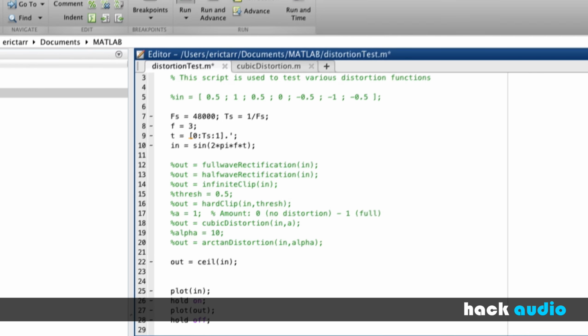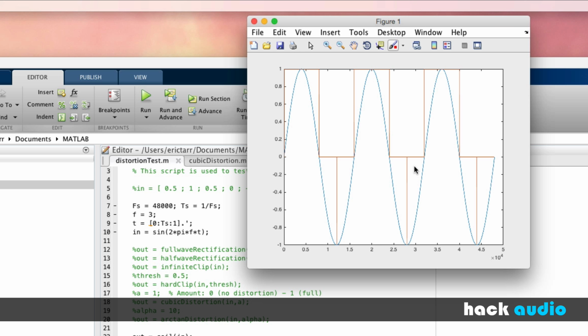It's going to round things up. So we're always rounding up to the nearest integer. As soon as our input signal has a value that's greater than 0, it's going to round it up to 1. It doesn't matter if that amplitude is 0.1 or 0.9. It always gets rounded up to the integer of 1. Then when we're within the range of 0 down to -1, we're going to round it towards 0. There is this exception though, when our input signal actually has an amplitude of -1.